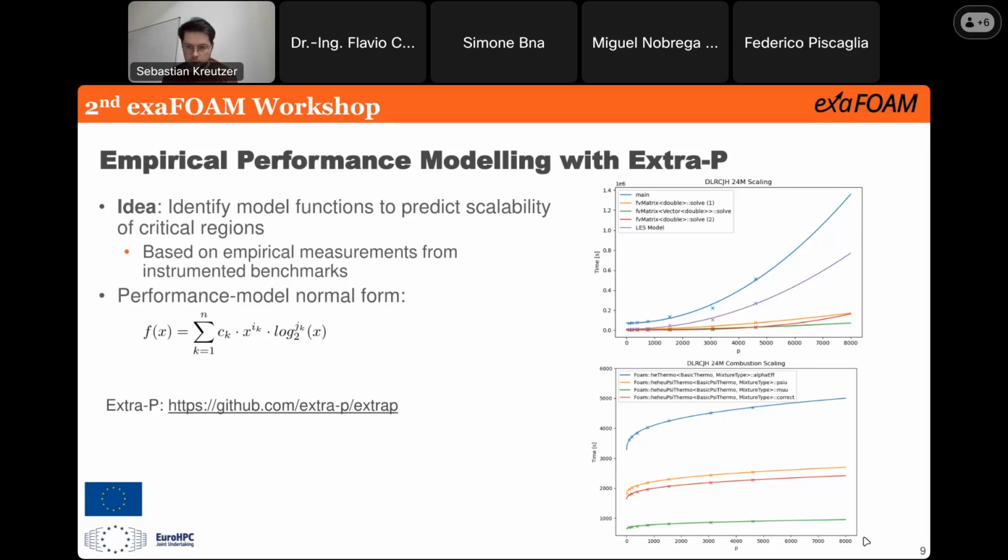On the other side, if you look at some of the reaction functions responsible for the reaction computation, they seem to be scaling much better. So we can see that this is a problematic function in this case. And it turned out this was the issue that was discussed earlier too, with the wall distance calculation that was inefficient for higher core counts.